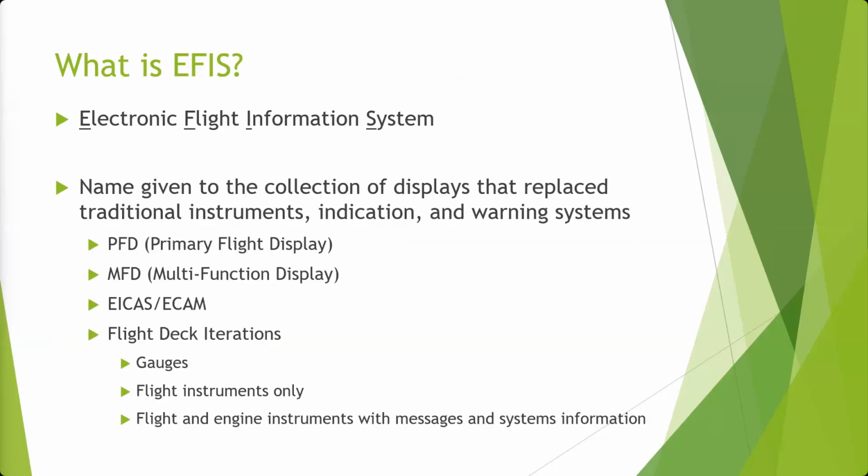Okay. So these feed in. We talked about our different generations of flight decks, and what you're going to see now, pretty much any modern flight deck, has what's called an EFIS system, or electronic flight information system. And this is not system information. That's the first thing I'm going to tell you. This really is not a system thing. This is more of an avionics navigation type setup, right? And these are the displays that replace your traditional instruments, that six-pack: airspeed, altitude, turn coordinator, heading.